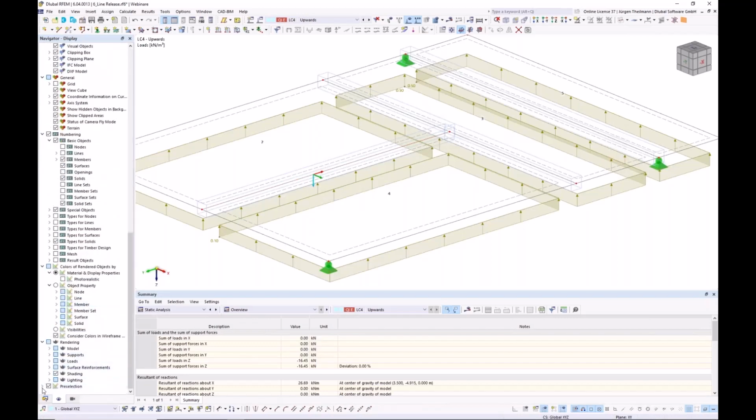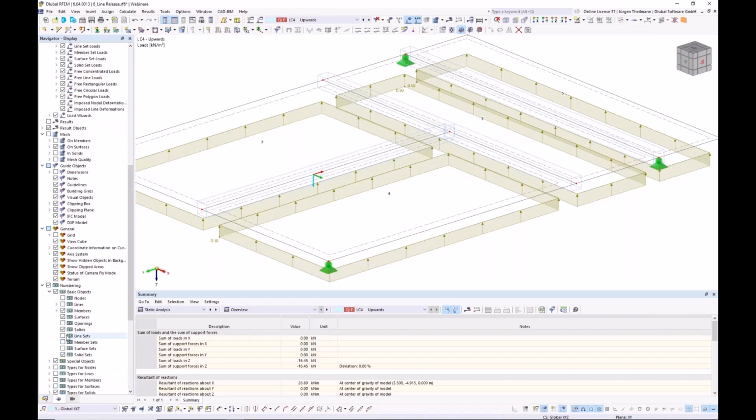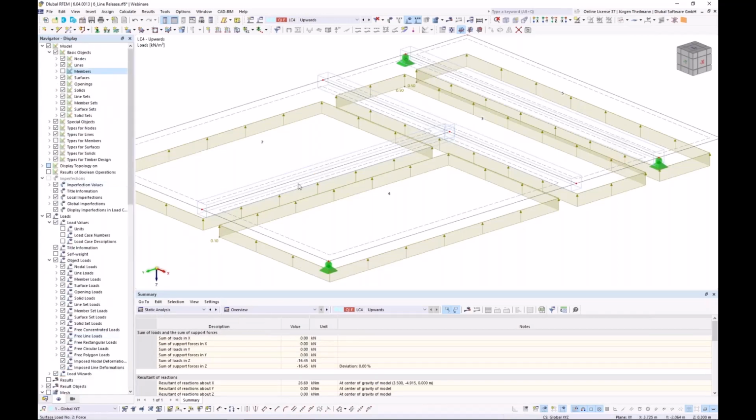Down to the bottom, and there's the pre-selection. If this is deactivated, just check this box and you'll have this pre-selection just as I have right now. So to get back to the point, line number 3 was the original one. With the release, I created a copy, which is line number 14. And the released surfaces now use this line number 14, and the member lies on line number 3.